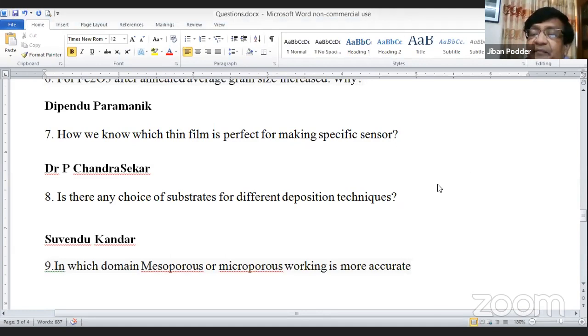There are many parameters to think about, and if we want to make it cost effective, we have to compromise on all of them. Normally we want a good, stable, stoichiometric, reproducible, non-toxic film, around 100 to 200 nanometers in size, which is then suitable for sensor purposes.